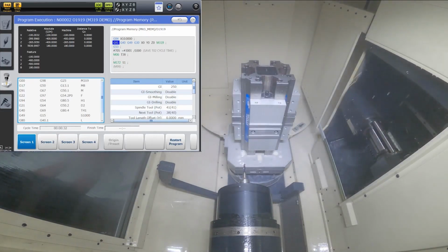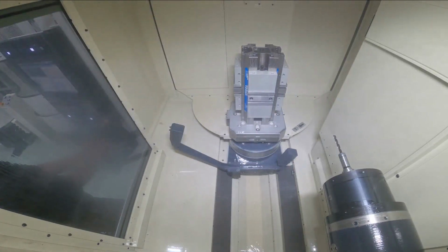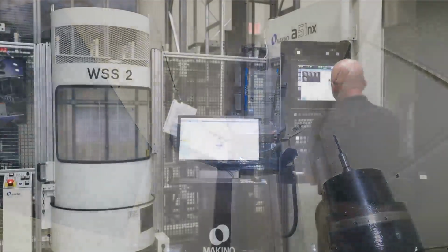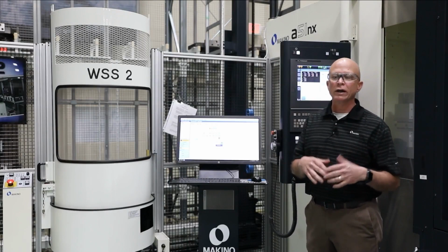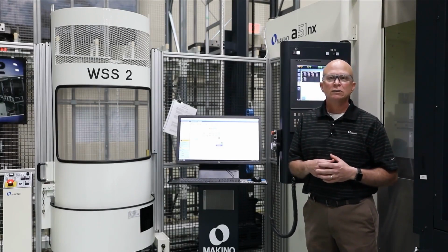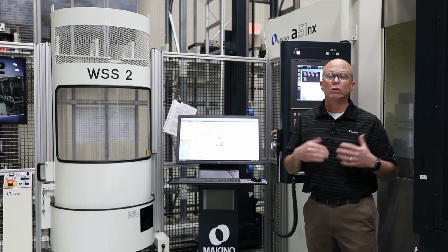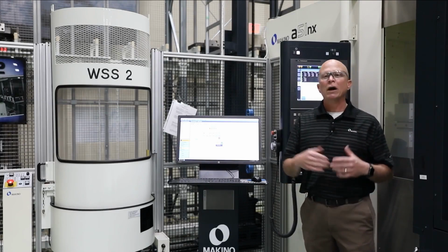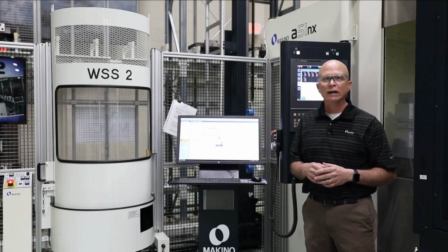All those processes, all those 4 steps just happened. I'm going to take single block off. It's going to move over to the tool change position and change tools. So now, as we mentioned, we're going to record this cycle time. I'm going to crank everything up 100% so we can get this time, and you can see the difference between the serial process, and then the parallel process, that Makino M code, very powerful, M319.